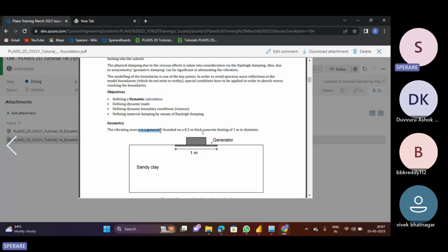So for that we need to go for bolting operations. Sometimes what will happen is, even if you bolt them, when you start the machining operation, suddenly your bolts will break, and because of that it will damage a part of your foundation too, the cement concrete foundation.